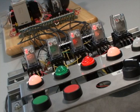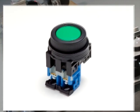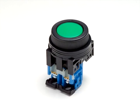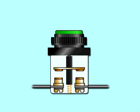Switches and relays are classified according to operation. The three types of operation are make contact, break contact, and changeover contact. Make contact is also known as Arbeit contact, which is abbreviated as A contact or form A. If A contact is not in operation, the circuit remains open and the off state is maintained.